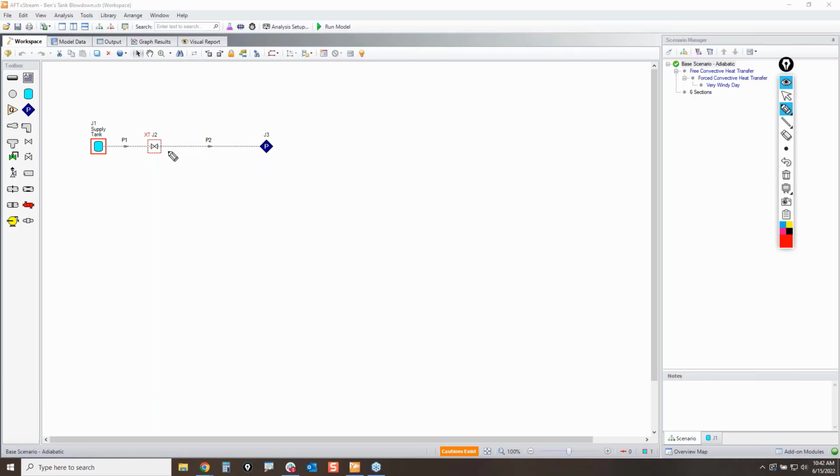So in reality, you're going to have a situation where you have air in your system, and as this valve opens, the nitrogen is going to have to start pushing the air out of the system before you start to see nitrogen exiting. That's what the model is going to show. It's going to show densities in this pipe based upon nitrogen, where in reality, they're going to be air densities initially until the air is evacuated. So that's a very important assumption I just wanted to make clear that we're dealing with right here.